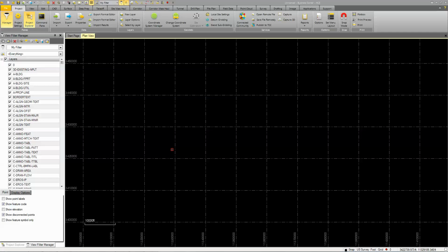The whole point is that your survey crew collects data, and using feature codes and line coding, when it's brought into the software application, the software will connect the dots, draw the lines, and place the layers and symbology in the project or drawing on its assigned layers, therefore automating the drafting process.